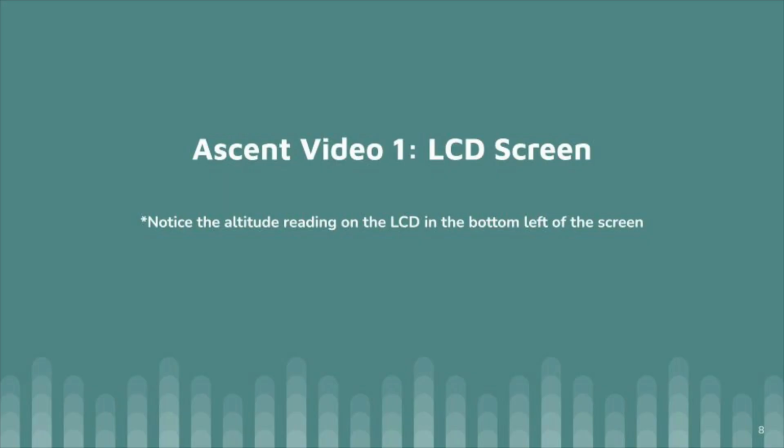So when we actually tested the system, we found it worked really well. The only thing was the Arduino did not have enough memory to support all the libraries from both the SD and the LCD at one time, so we could use only one or the other at a time. So we decided for the ascent we would use the LCD, and for the descent to use the SD card and log the data, which you'll see later. So here's a video of the ascent in the LCD.